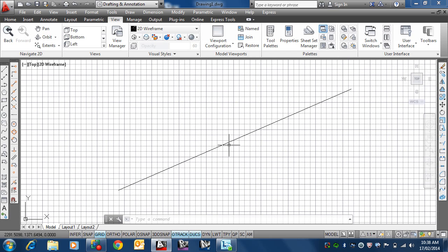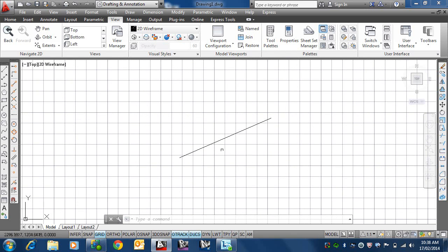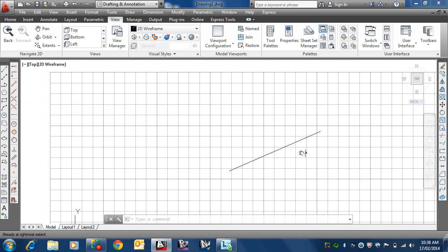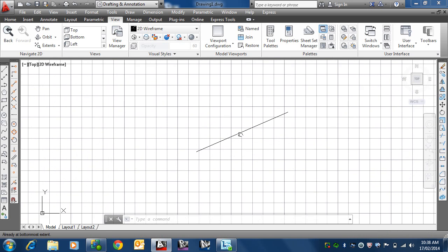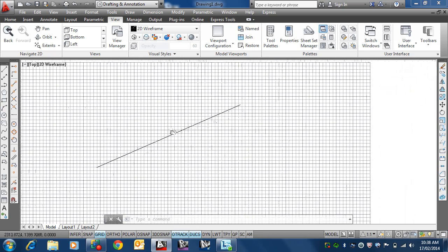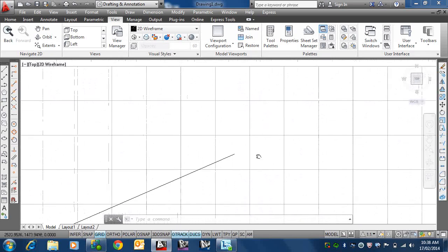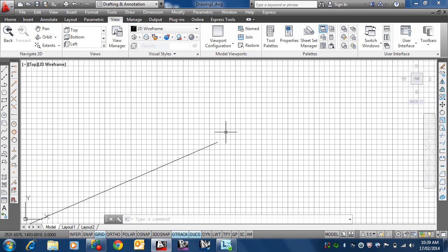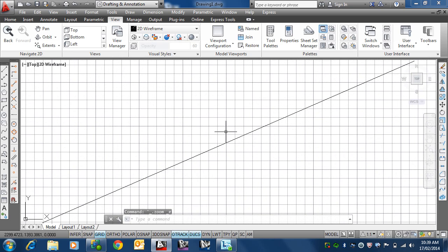The other thing you can do is pan. If you hold down the middle mouse button, which is a scroller, and move your mouse, it'll pan. So it does three things. It does a zoom in and out. It does the pan, and that's how you end up going to the right spot in your drawing. That's what you do all day, so you learn to use these. And it also does a double click, which is the zoom extents. Sure, you can use these buttons here if you prefer, or you can use these buttons from the View tab, but I find that a lot slower.